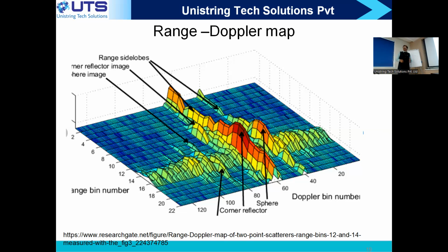This is more implementation level, but what is the bin resolution in your FFT? We took that example, right? 1 megahertz, and you did a 256 point FFT, then from one X(k) to the next X(k). Of course k goes from 0 to 255. But in actual frequency terms, what is the separation of two adjacent values?